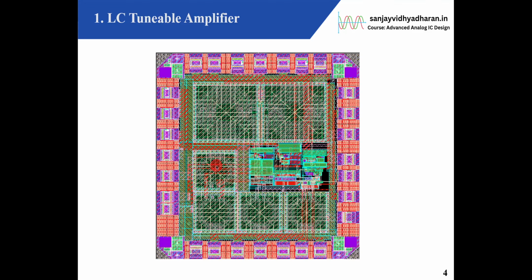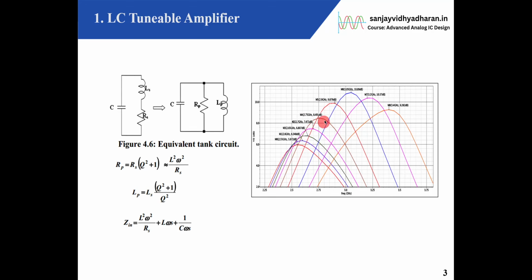This is a 0.5 nanoHenry inductor. So inductors occupy a lot of space. There are two drawbacks in an RF microelectronic tuned circuit which employs spiral inductors: one, it consumes a lot of silicon space, and second, the quality factor Q is bad.